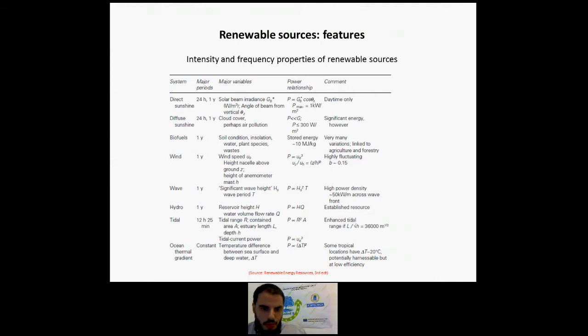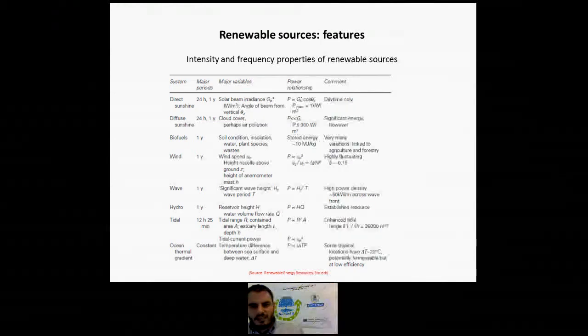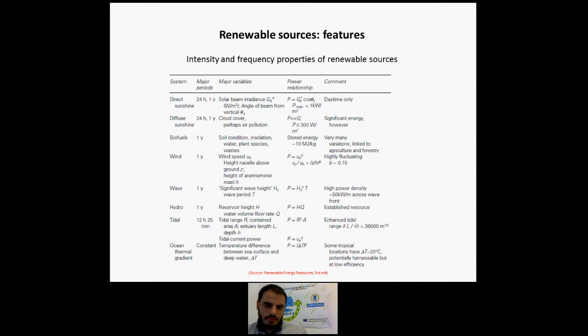Meteorological data are always important, but unfortunately, the sites of official stations are often different from the energy generating sites, and the methods of recording and analysis are not ideal for energy prospecting. However, an important use of the long-term data from official monitoring stations is as a base for comparison with local site variations. Thus, wind velocity may be monitored for several months at a prospective generating site and compared with data from the nearest official base station, while extrapolation using many years of base station data may then be possible.